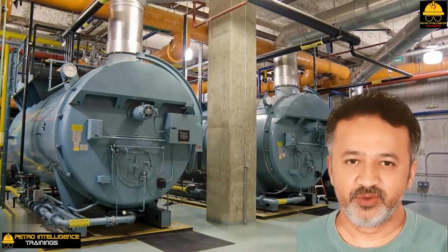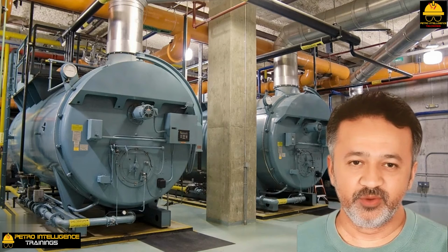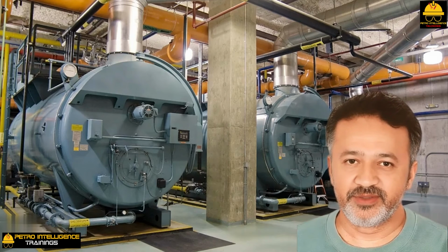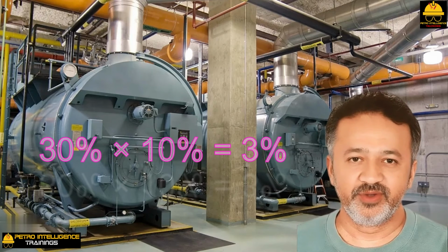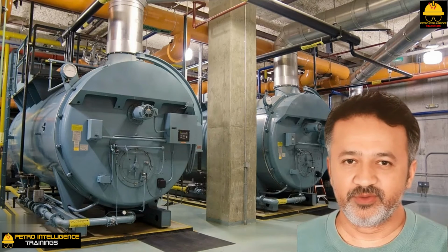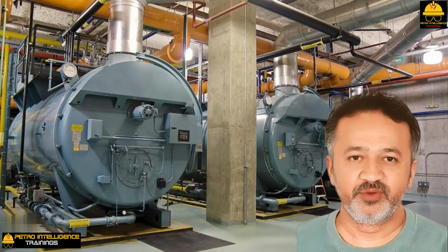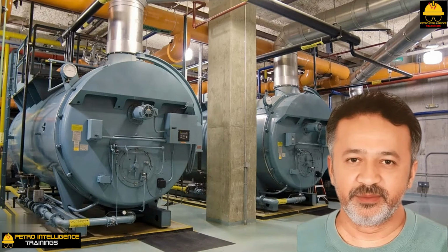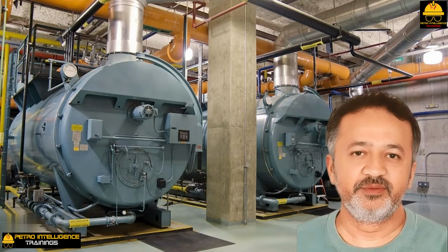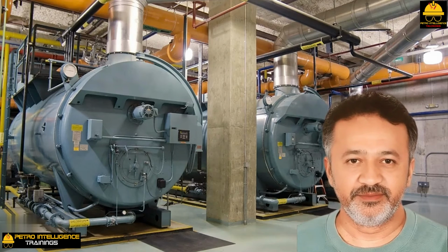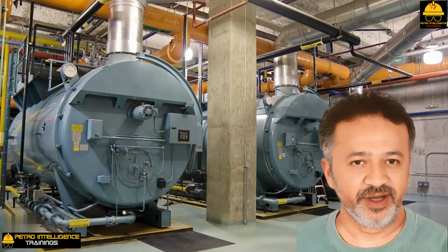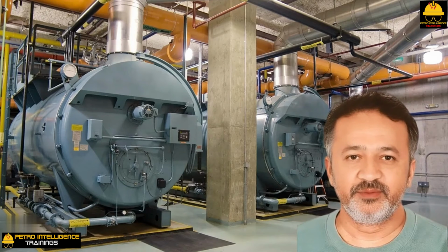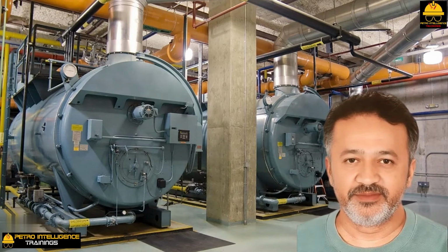As the convective section duty is typically 30% of the total boiler duty, a 10% reduction in the flue gas rate will reduce total boiler steam production by 30% times 10% equals 3%. Of course, you are also saving 10% of the fuel gas consumed for each pound of steam production, so perhaps the 3% boiler capacity reduction was acceptable. That 3% is the price we have to pay for energy savings. Combustion air preheat in boilers, which are limited by excessive radiant section temperature or hot tubes, will always lose steam production capacity due to the air preheater.